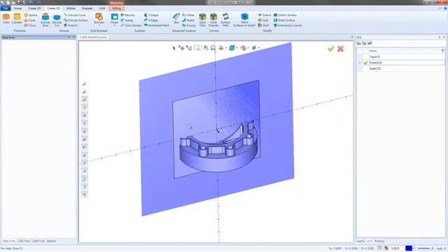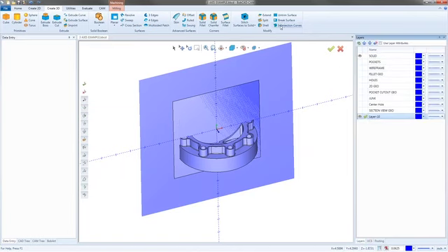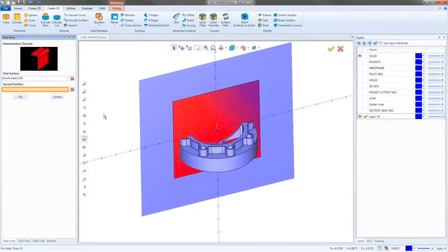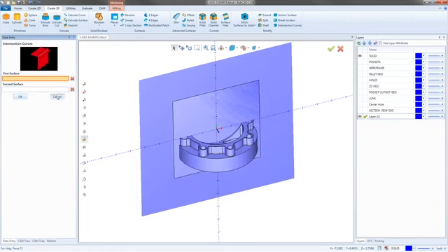And so all I did there was create a plane that's standing in the front plane position, and then make sure that plane is big enough to cover the entire part. Because now I can go over here, make sure my check mark's on that layer, go up to intersection curves, and I could say, here's my first surface. I want to find out where that surface intersects this solid down here. Then I'll hit OK and cancel out.